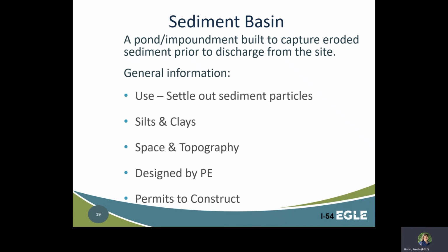There needs to be adequate space and appropriate topography in order for an effective sediment basin to be constructed on site. Sediment basins take up a lot of space on a site.